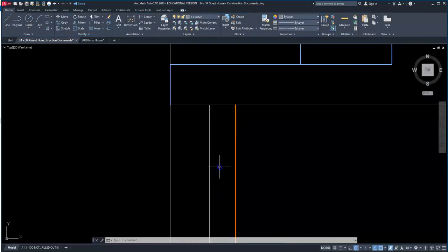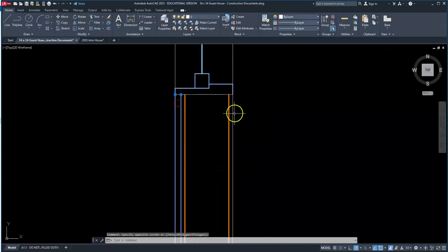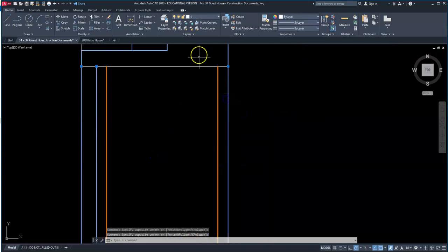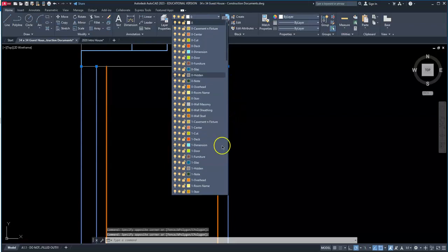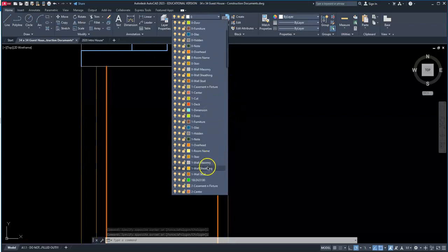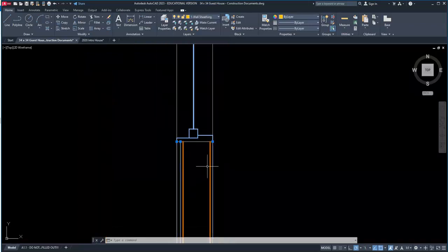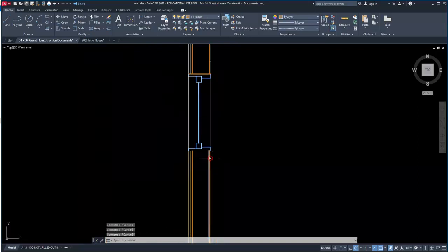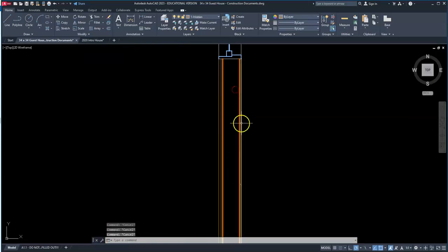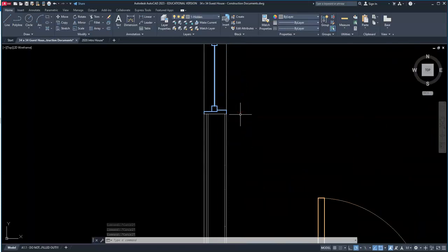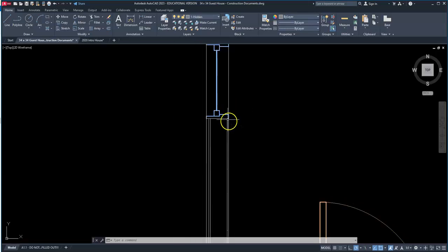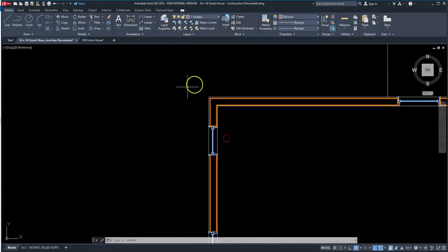And for the sheathing lines, we'll select all 3. Same procedure. Choose the lines and then go to 1 wall sheathing. That's going to give it the orange lines. Now remember, when we print these, they'll be black and white. So it'll be on white paper, we'll use all solid black ink. So the thickness of the lines matters a lot to give that depth perception. So continue on. That's exterior.